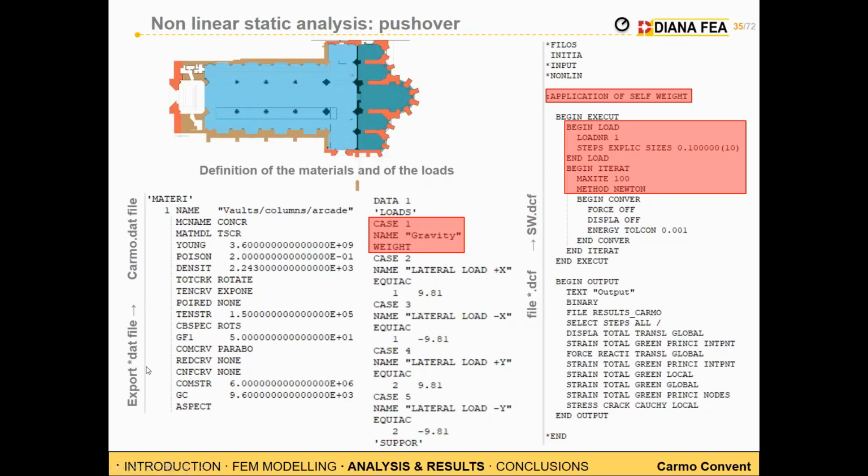which contains all the information about the geometry of the model, and also we can add other kinds of loads directly in the DAT file, as if we were typing in Word. It's very easy. But it's important to select the proper strings to attach the correct loads and avoid the following problems.